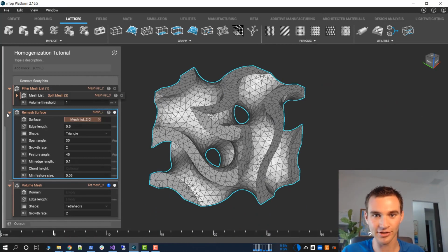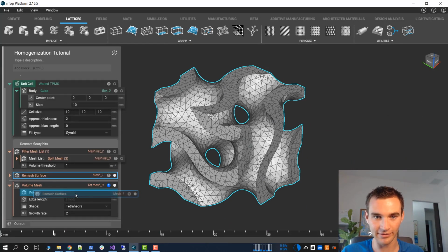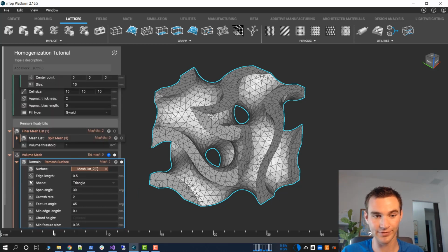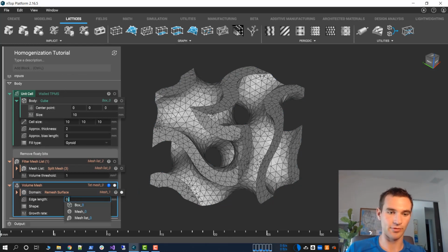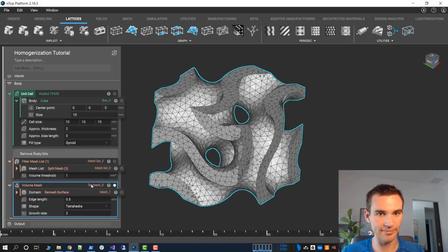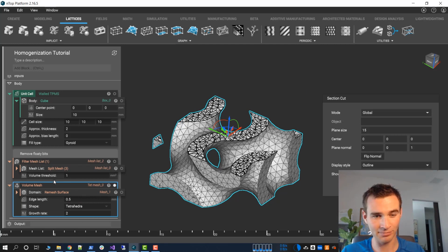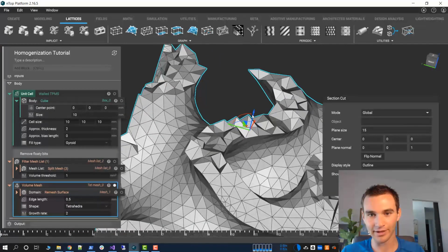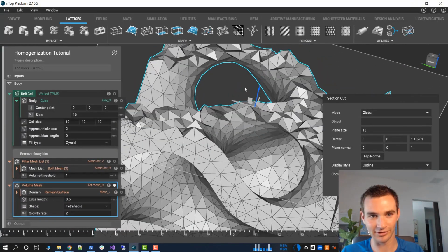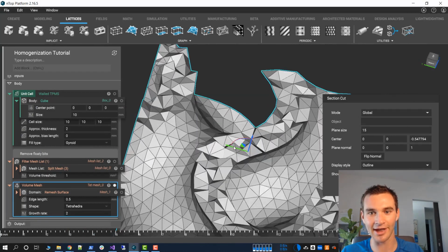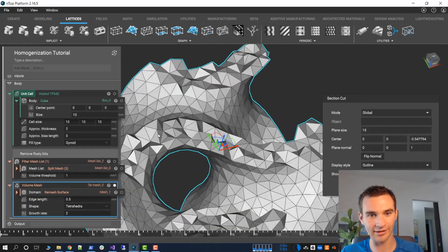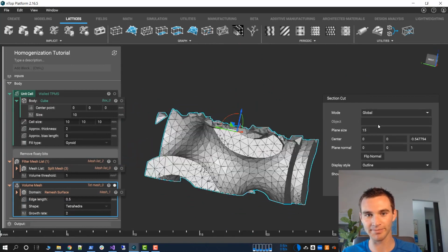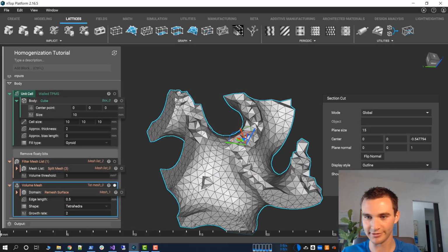So we've got a surface mesh. We need to fill it with volumetric elements. So I'm just going to match my edge lengths here so that they're nice and uniform. 0.5. So this will fill it up. You can actually now, in nTop, press X, and you can see what that looks like almost as if it were like a rock, and you break away the grains, which is kind of cool. You can see the tets inside are pretty nice. We're going to come back later and make them smaller just to capture any deflections within those thin walls, but again, just for starter's sake, this should be good to go.